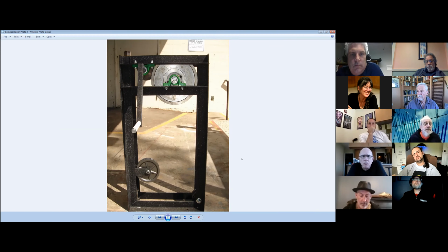For small venues, community theaters or college theaters, something like this can drive not only wagons across the stage, but you can use it on a turntable as well. And that's why this has 2 speeds. You have this geared system here to haul heavy freight on a deck, and then you have this direct drive. You can change the handle from here to there, so you're directly driving this pulley here for a turntable, because the ratio between that pulley and the turntable is so different. They have a good mechanical advantage.